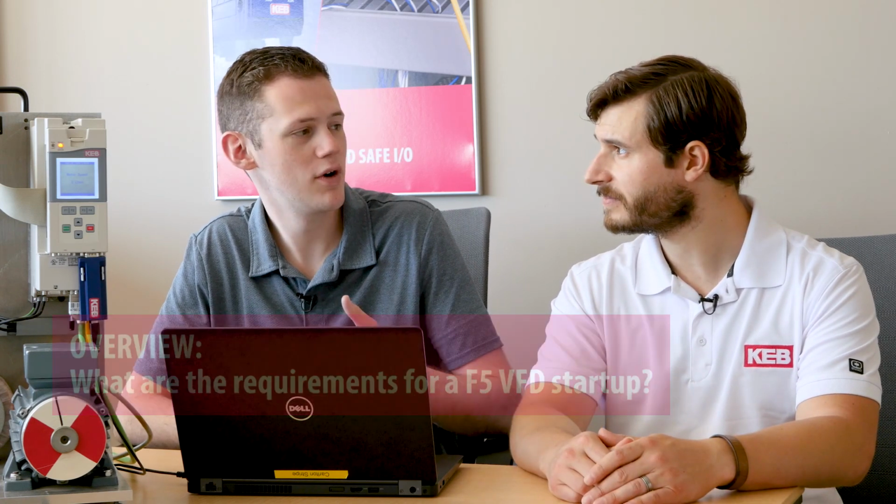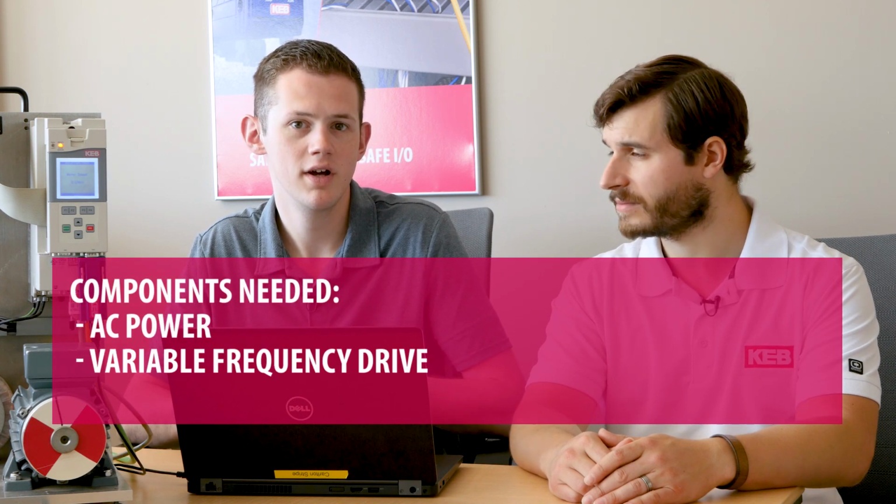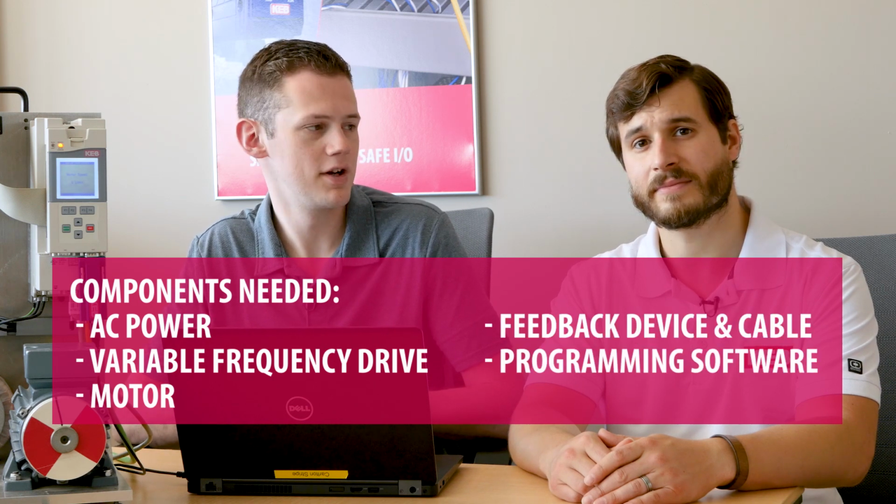Yeah, Jake, similar to our startup video with the S6 drive, we'll need our 5 basic components to start up a closed loop drive with an F5. We need our AC incoming power, our KEB F5 drive, a motor, a feedback system for speed control, and our programming software to set up the drive.